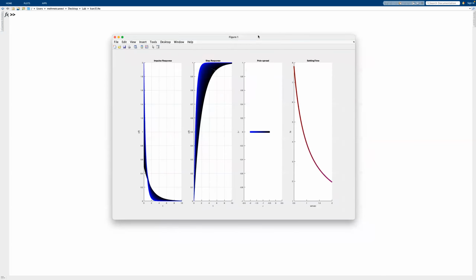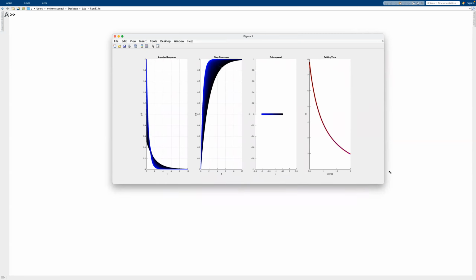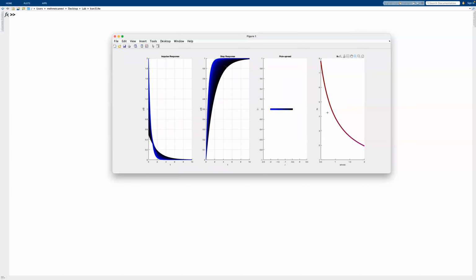So this is basically the maximum analysis that I think we can make about a first order system, because it does not have that many capabilities. It has only its settling time. It doesn't overshoot. When we go to the left on the S domain on the real axis, it speeds up, and that's basically first order systems summarized.